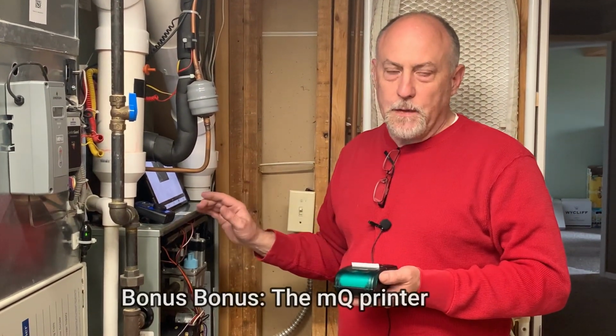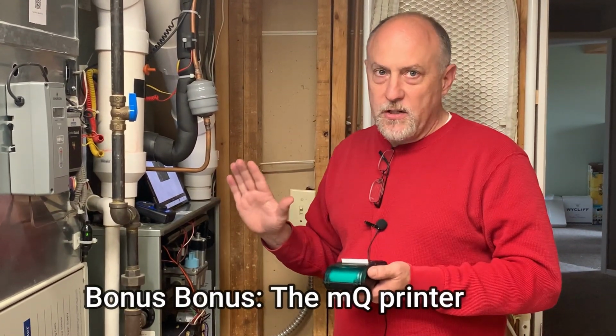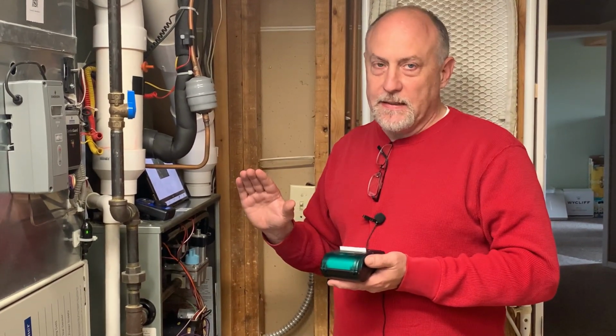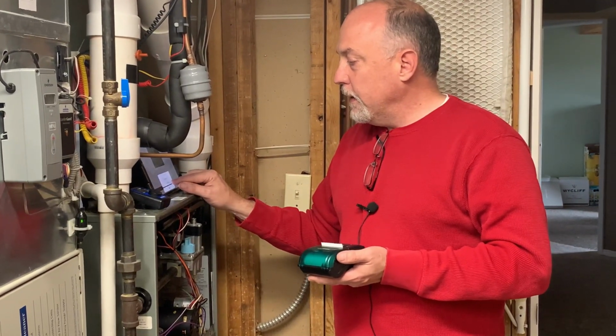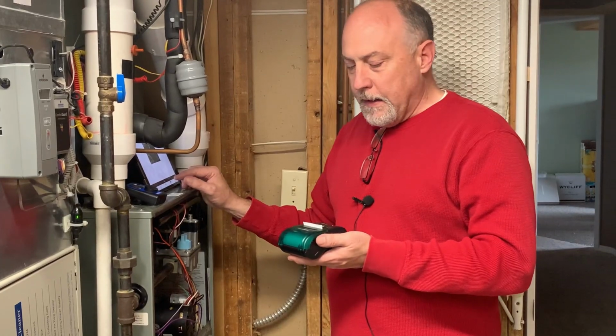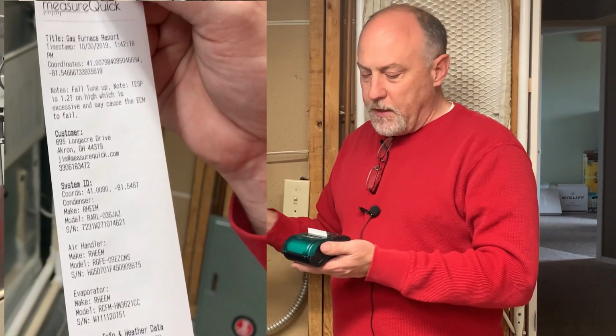So we're all done. You want to make sure you print out a copy of the results. The great thing about measureQuick is you can print the full furnace test and not just the combustion test. A lot of municipalities, like in the Massachusetts area, require that you have a printout of the combustion results. But again, we can print the whole thing out by hitting share in measureQuick, hit print to the measureQuick printer, and this thing will just spit this out pretty darn quickly.